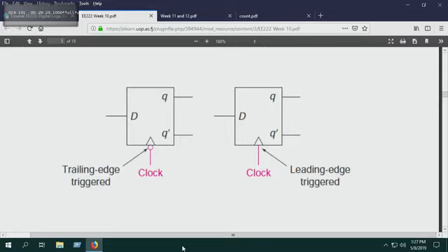So then we just took it to one of the other normal mechanics, not to those two guys. Took it to another mechanic. We opened the valve up. We cleaned it; the valve was blocked. You know, there's this carbon cleaner. Sprayed it, flushed out all the carbon, put that back in, and then when I turned on the car, it was revving higher. It's revving at 3,000.